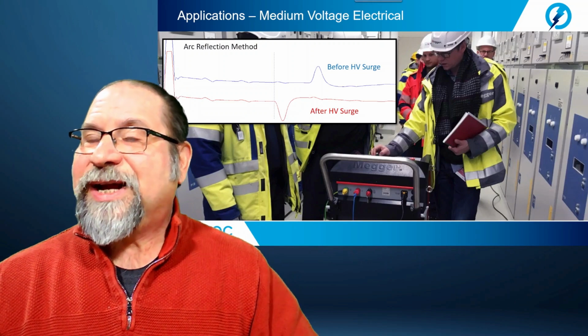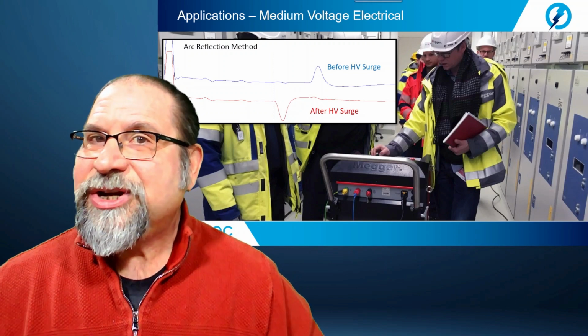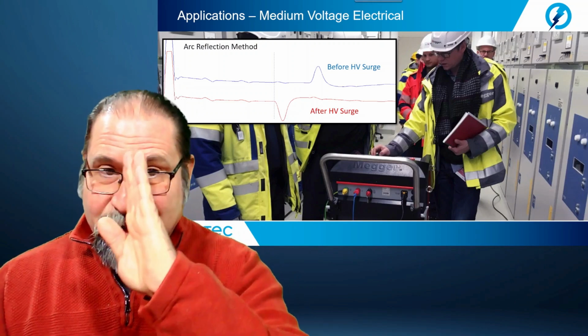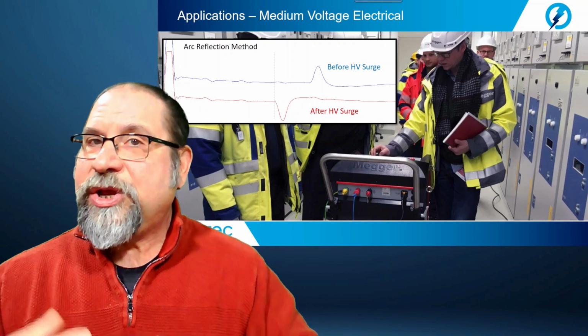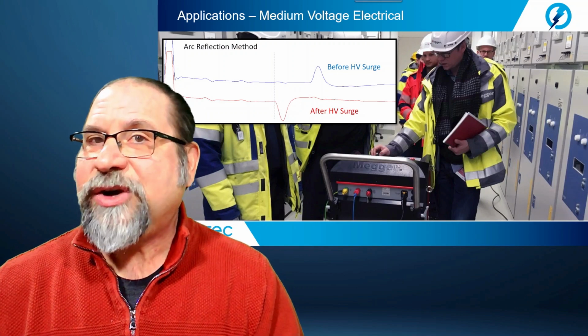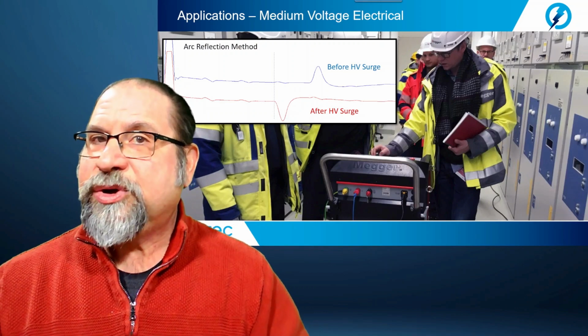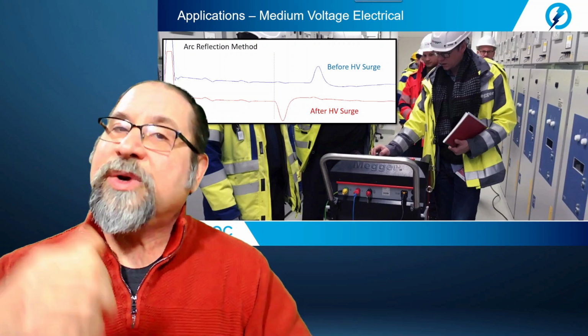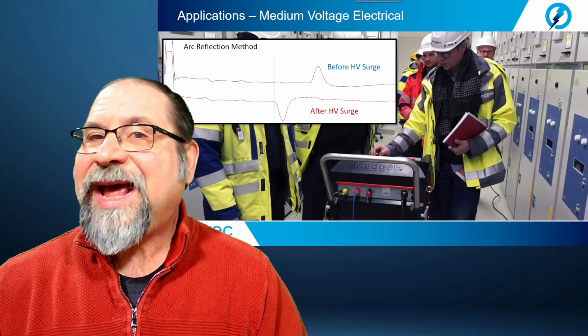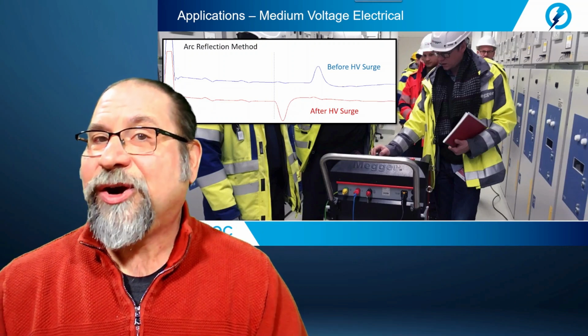We utilize the low voltage technology to allow us to peer into the cable and see events. We use the high voltage surge generator to reproduce the conditions to create the fault event, reduce the impedance to 0, and capture it with the TDR pulse.